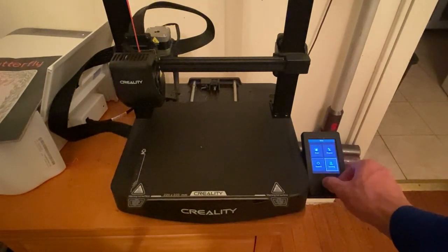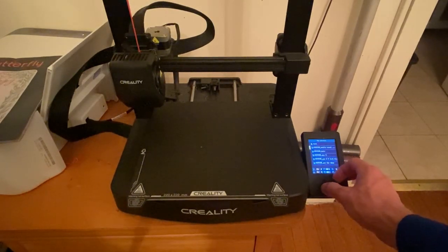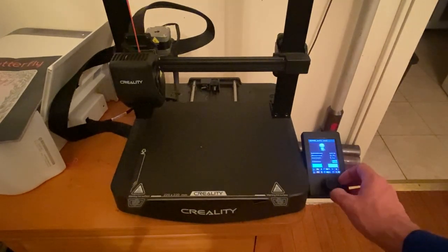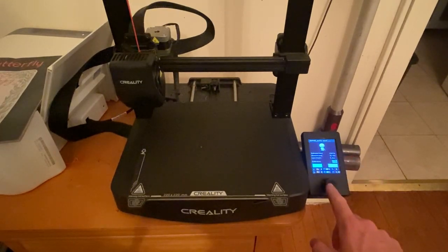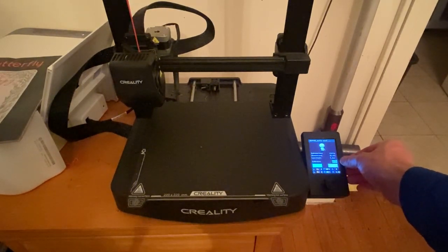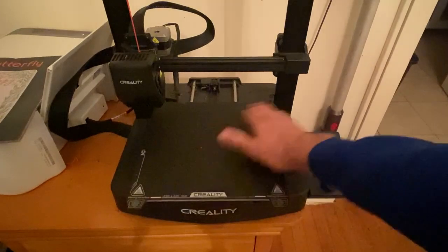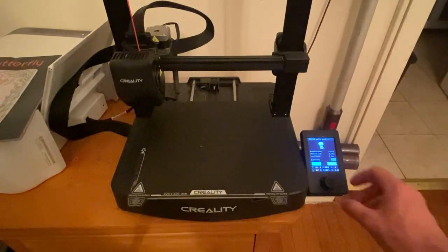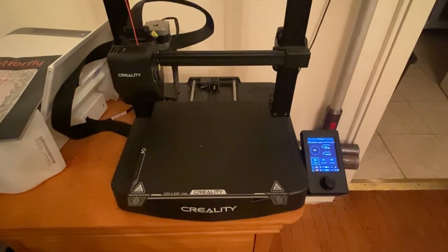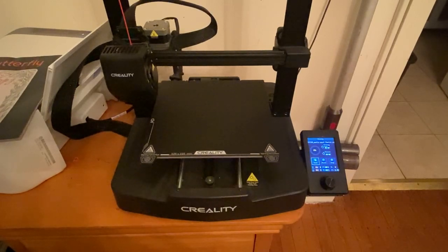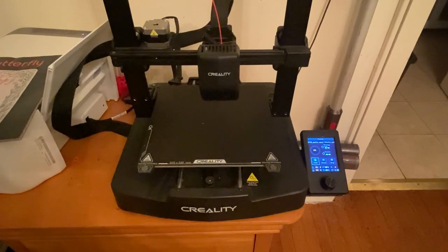So yeah, you have four options initially, and so you'll go to print, and then you'll go to the file that you want. You can select it, and I'm actually going to put the calibration on, so you make sure that the bed leveling is on. Make sure the build platform is free of any debris or anything like that. And then I can go to confirm, which will start my print. It'll start out by doing a bunch of limit switch stuff, and then finally start printing. So I won't bore you with all that.